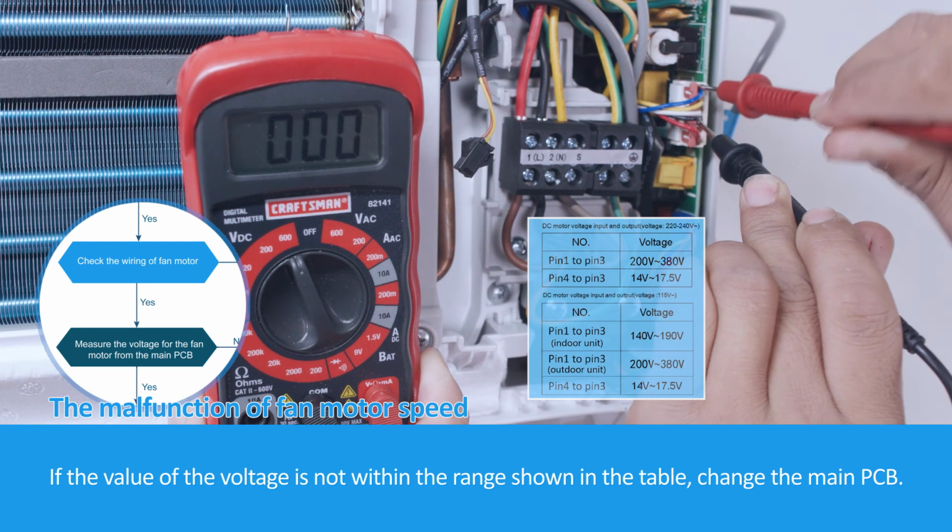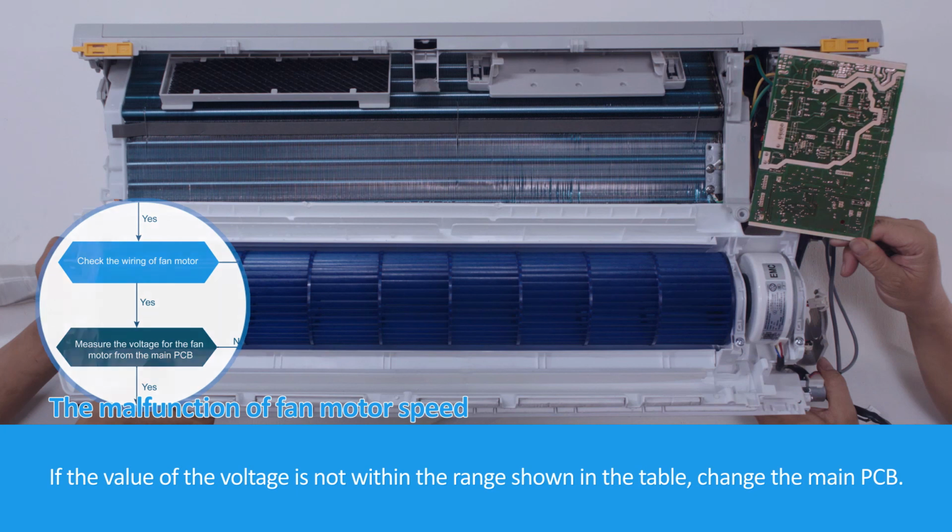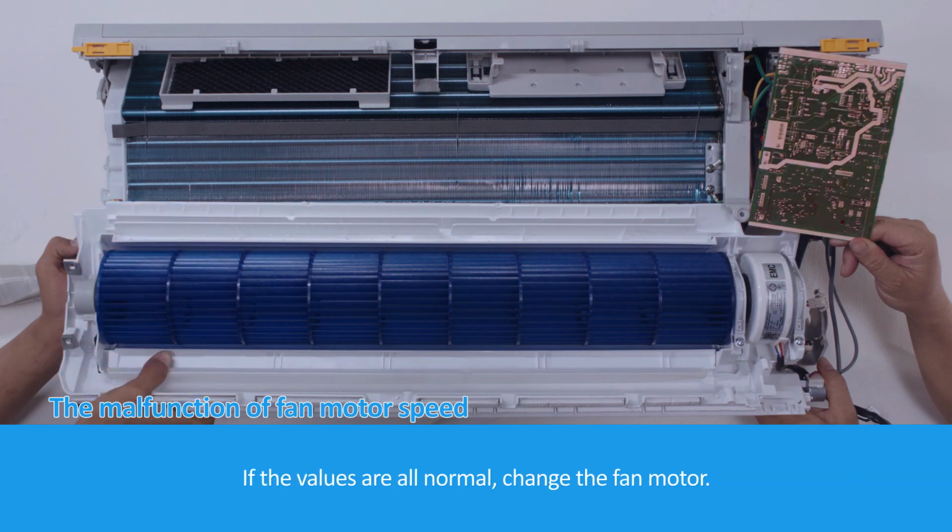If the value of the voltage is not within the range shown in the table, change the main PCB. If the values are all normal, change the fan motor.